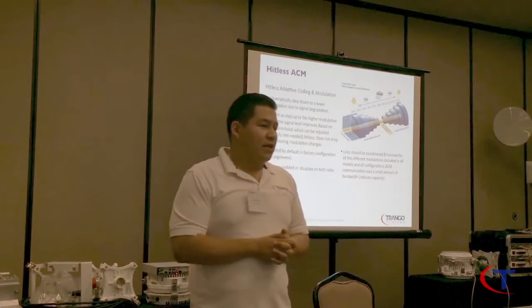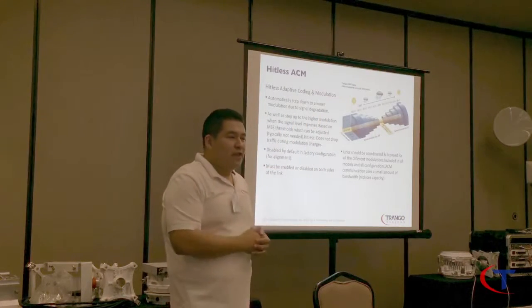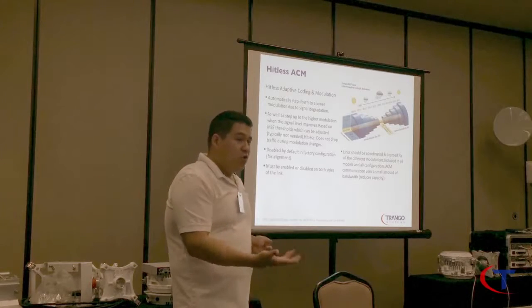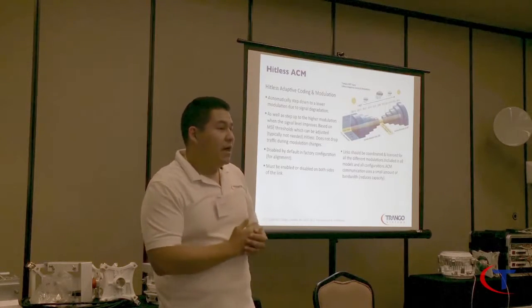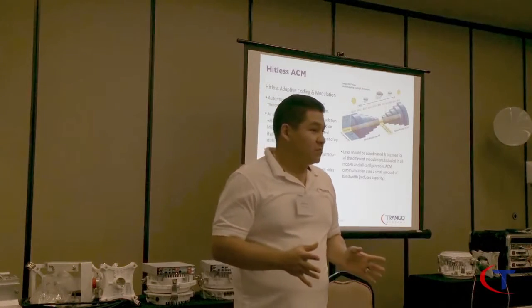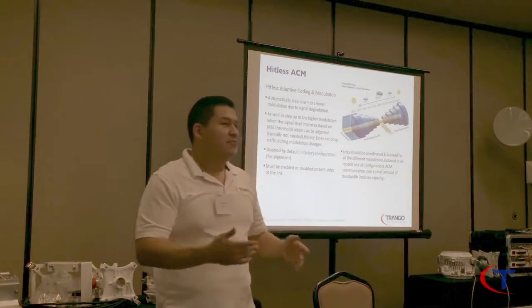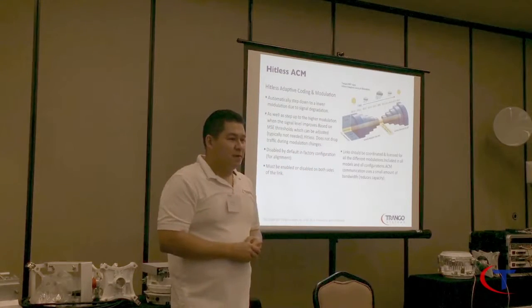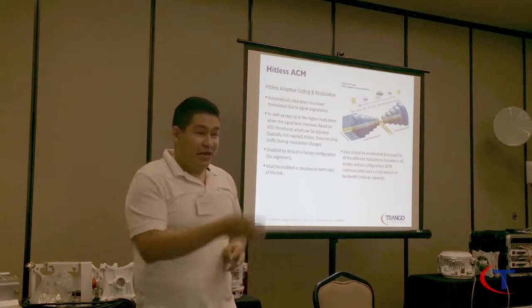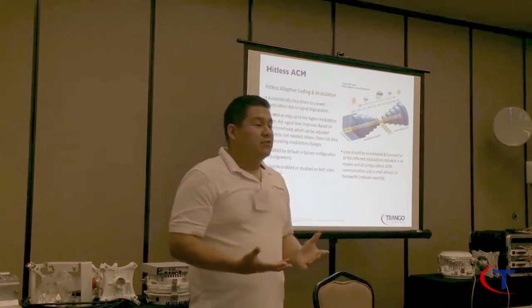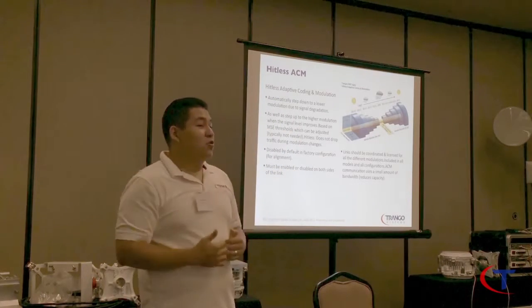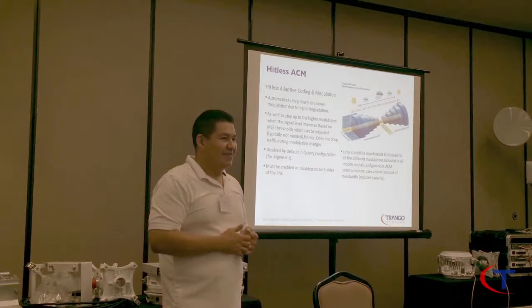Set thresholds. Correct. Typically it's from QPSK. When you align the new radios, you can set both the min and the max to QPSK for alignment purposes. After that, you can go back to 1024. When you do any changes, typically do the far side first, then the local side, so you don't get cut off.